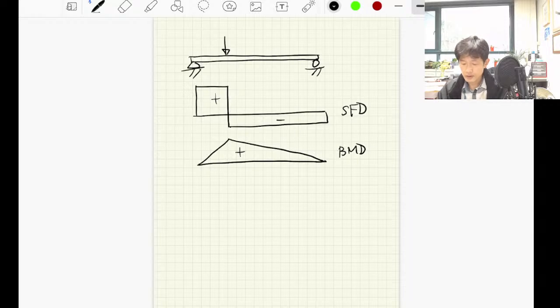Look, once we have the bending moment, for example, we can measure the bending moment at various positions. Let's say this is the x-axis. At different positions, we may read different values of bending moment. Let's say we are interested in this maximum bending moment. Then my bending moment divided by the section modulus should be equal to or less than the allowable strength value.